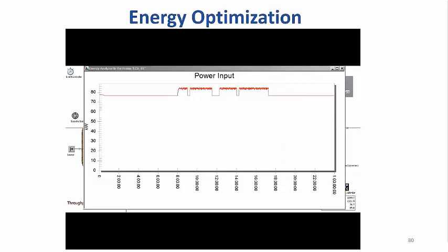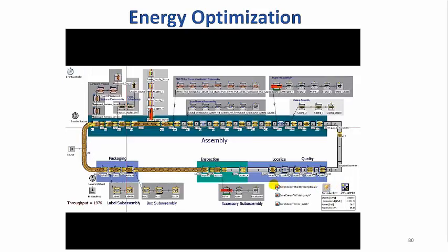After looking at this chart, you may have guessed that we could save energy by switching to standby during breaks instead of leaving everything in the operational state. To do that in our model, all you have to do is check the on-screen Save Energy Standby During Breaks checkbox. Now, after running our model for 1 day, our Energy Analyzer's display panel shows that we've decreased total power consumption from 1,899.7 kilowatt hours to 1,820.9 kilowatt hours. This would result in a nice decrease in your energy bill over the years.